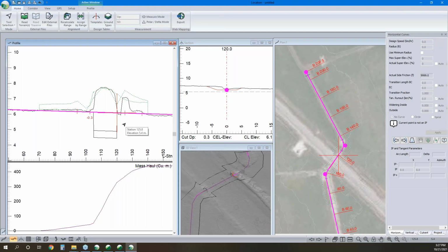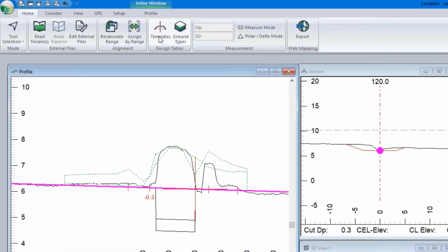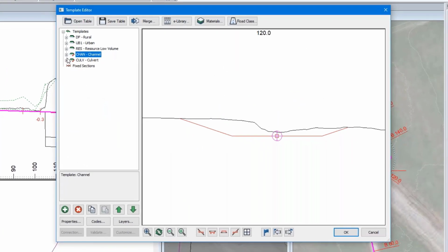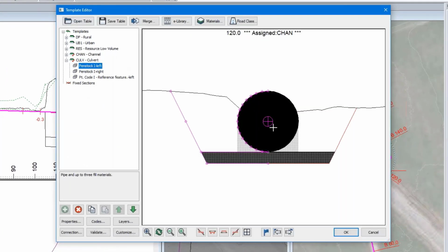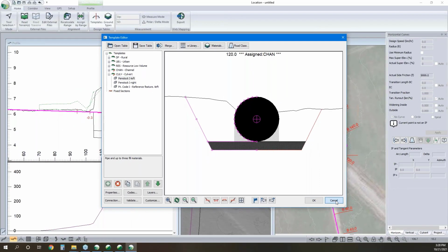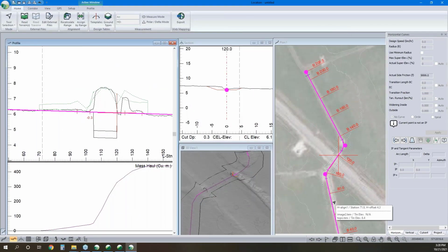Now with this, where I want to include an embedded pipe, when I built my template, I have it set so my culvert center line is at the center of the pipe. So here I've got an embedment depth of 50% my diameter. You could play with the attachment point to put that however you'd like. But with this, I don't have to put a jog in my profile. It's just offset to be lower than the rest of my profile. So it makes it easier for designing pipes.